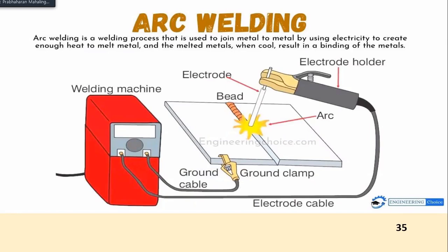So spare parts are important. A welding machine is available, an AC/DC machine or anything, anyway, electricity. So you can set the amount of amperage allowed for this machine working. Normally we have a 70 to 120 amperage machine. So normally we use the 80 ampere level for welding.